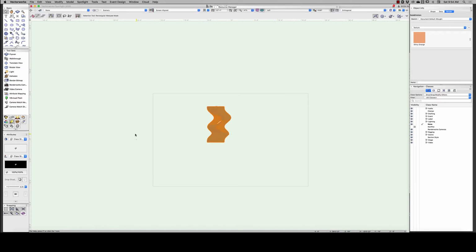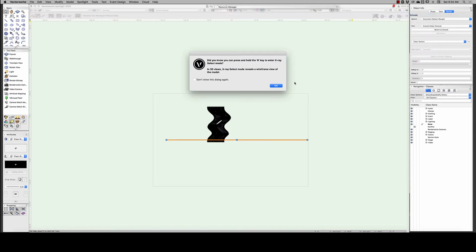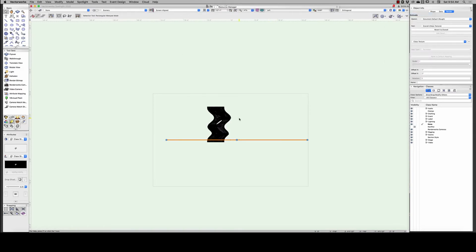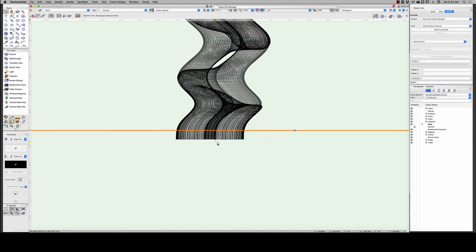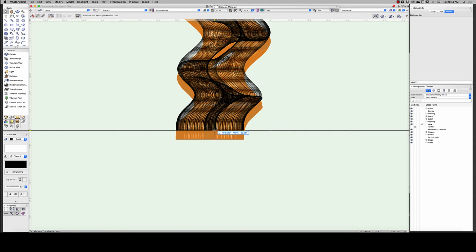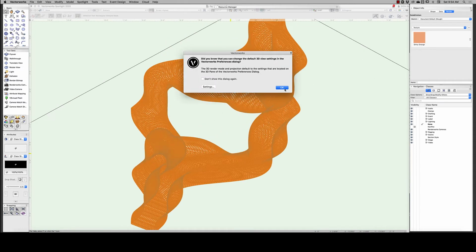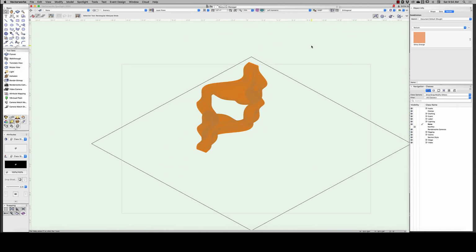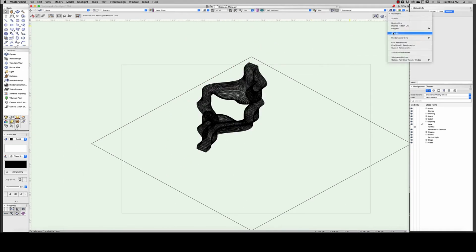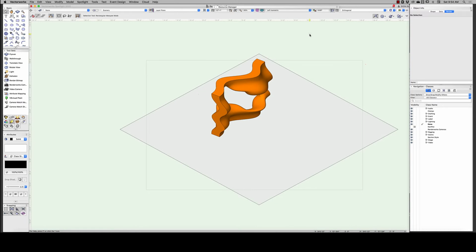That appears to be the way that it is situated in the model. The thing about the zero extrusion is if you're in a standard straight on view, so front or side, and are in any of the rendering modes except for wireframe, it doesn't show up because it has zero thickness. It will show up in wireframe. So we're going to move the wall up so that it's sitting right on the floor. So we currently have this. Go to OpenGL just so we can see what we have.